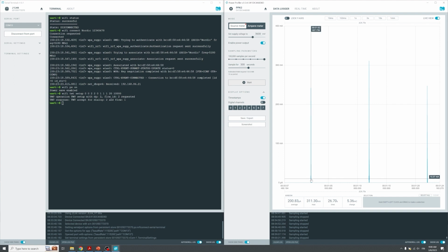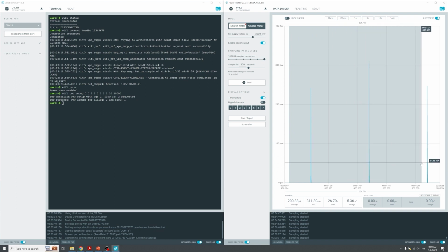So let's go ahead and measure this. So hold shift and scroll across. So now we can see it's 10 seconds. And if we want to see the impact on the average power consumption, we have now taken even another step improvement compared to legacy power save, and we're now at a 200 microamp average power consumption level.